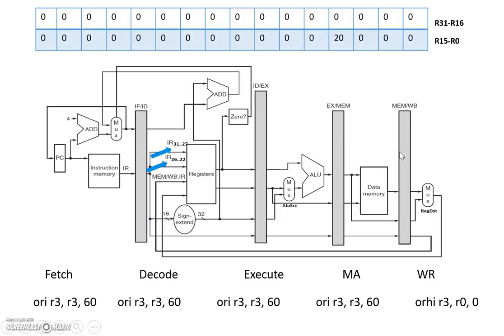Now a new instruction is accepted and old instructions are passed on to the next stages. Again, because of data hazard, stalling is done, and instructions are passed on to the next stages till the write back happens. Now in this stage, the new value is put in the register file, and we will get value 60 in the register R5.